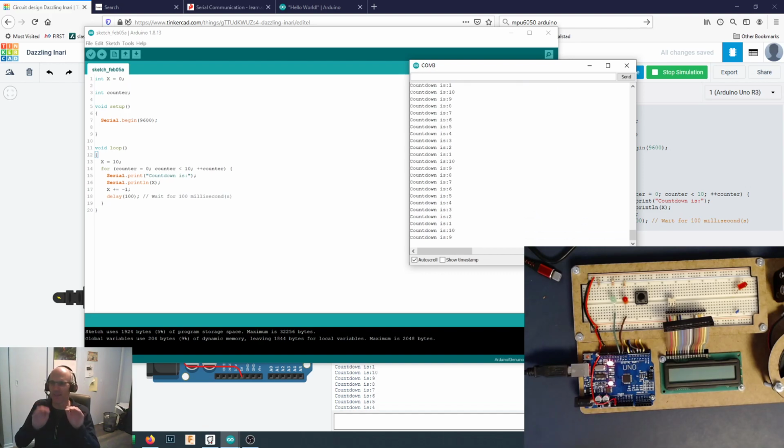You're getting something in there, but it doesn't know what you're saying. If you've got the baud rate right, they're both speaking the same language at the same speed, and they know how to talk. Well, now you're getting data off your Arduino. This is really important because later on we're going to attach sensors to our Arduino, and you're going to want to be able to read the sensors. Transmitting data over the serial port is one way to get data off of your Arduino. You can also use the serial port to do all sorts of interesting things. Later on, I'll show you how you can use your Arduino to actually control things on your computer. There's some really neat stuff that you can do over the serial port.